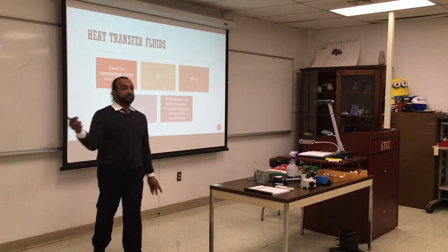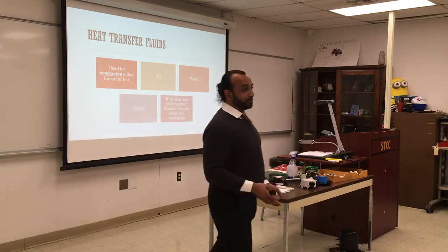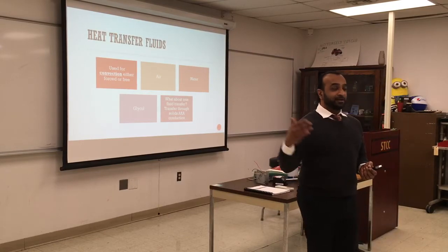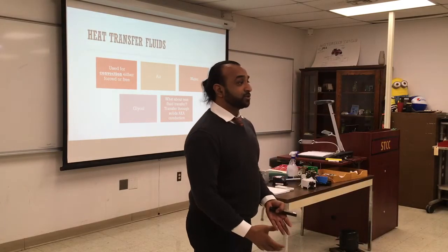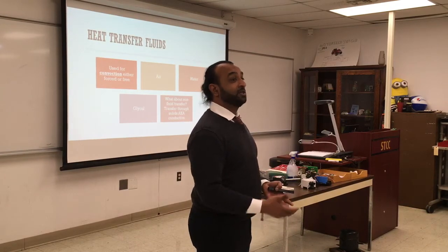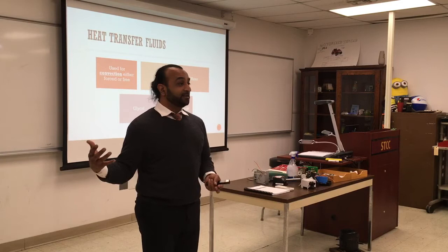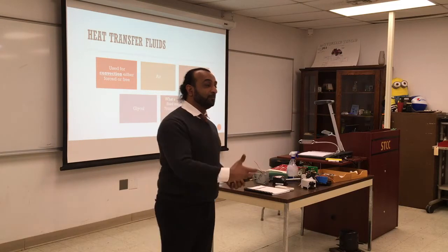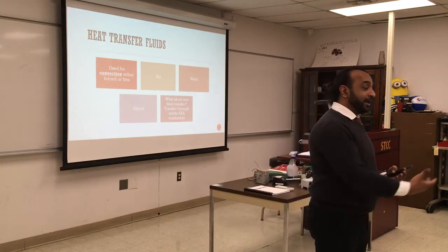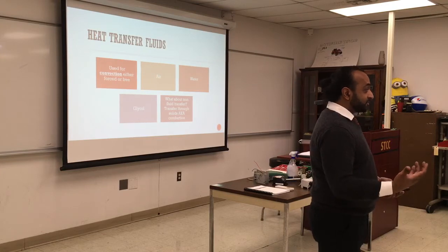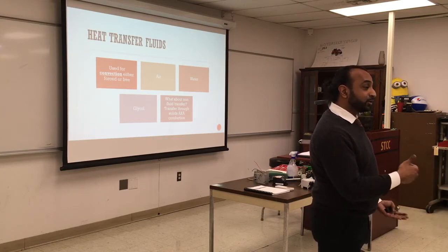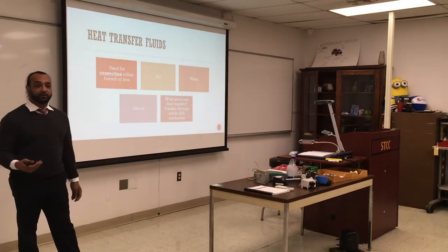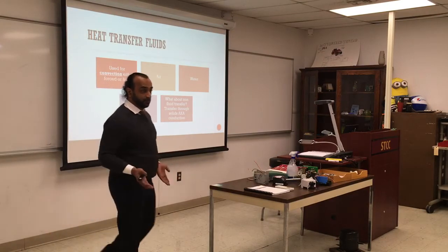So your car, if you can understand your car heating system, how does it work? You can understand a hot water system. You have your radiator outside. You have the engine, which is your heat source, internal combustion. You have another radiator inside, a heat exchanger, to pump the hot water into, and the air from the AC circulates around it. So if you understand that, and you have the thermostat and control air in and so forth. And the radiator fluid tries to get rid of the excess heat through the radiator.